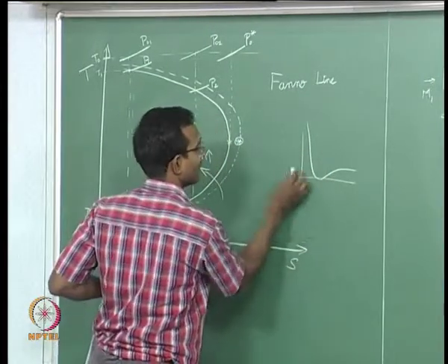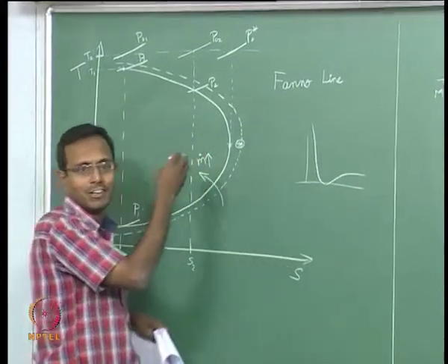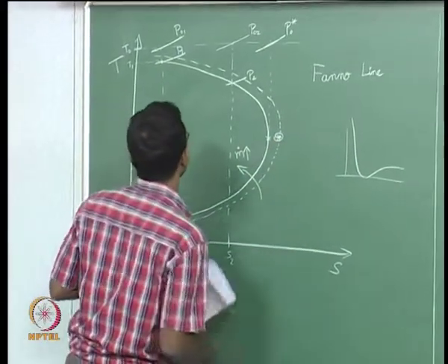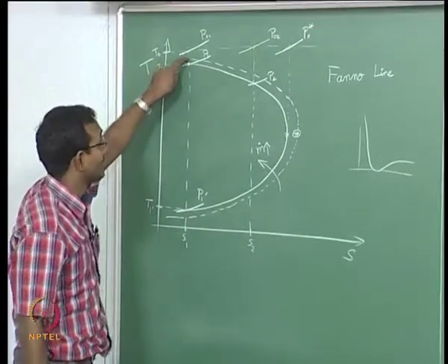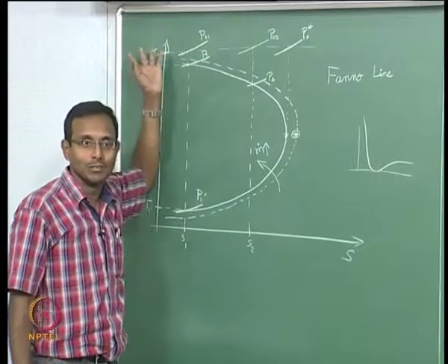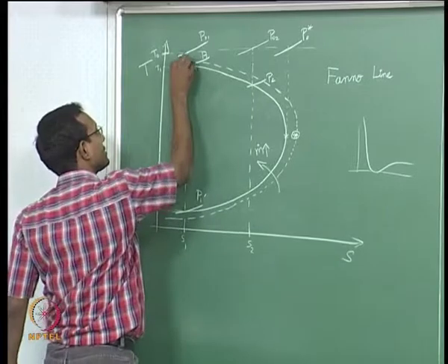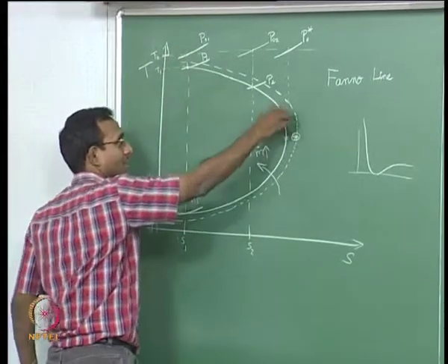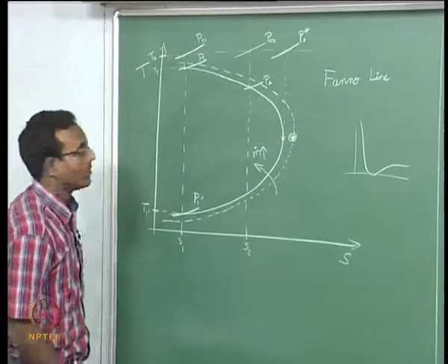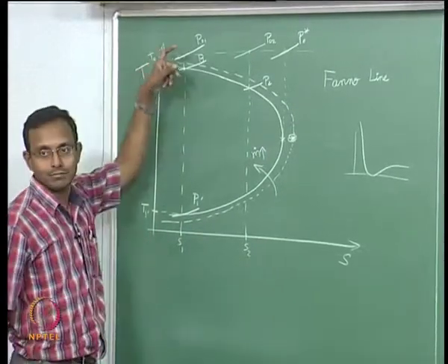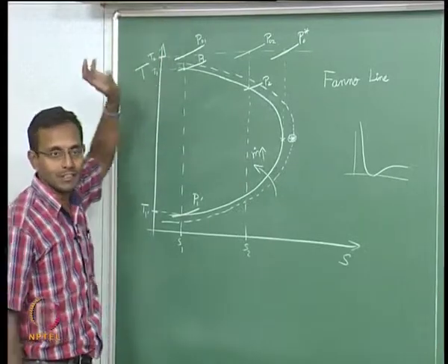If I decrease my Mach number, my L star increases further, f L star by D. We keep f and D constant, so L star increases. So I go to a lower Mach number as starting point. Now my L star is higher. That is the reason why the flow wants to do this. Okay, it has gone there. Okay. So now it chooses some particular curve such that it will come and make it just L star at that point. So it will go on choosing till that point. It will not go any further above. That is the idea here.